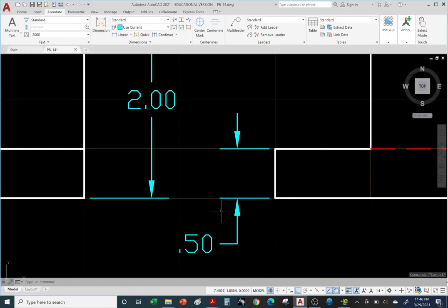Okay, it's okay to move a dimension outward. I could have also gone upward, right? Another option is to place the arrowheads inside. That's another option. I can flip the arrows. As long as it doesn't look crowded, that's acceptable also, okay? So either of the three is acceptable: arrows inside, or text inside, or all three outside, okay?